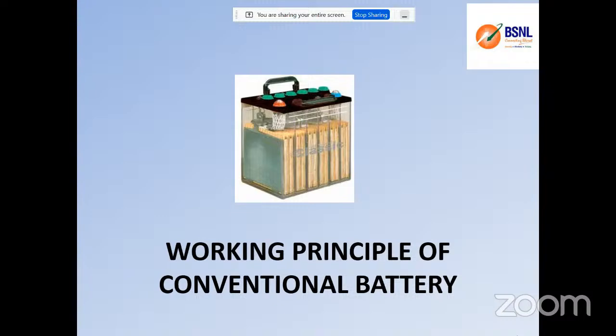But at residences, because of affordability and the cost-effective nature, though the UPS methodology is available, not all the loads are critical loads. So we neglect the non-critical loads and use the inverter model. So that, okay, if this goes off there is no problem, so I don't need battery backup for it, and even a smaller battery backup is enough for me, since I have only very limited critical loads. That is why the UPS models are segregated. So inverter models are more popular in our industry. Hope I made it clear about the logic of both UPS and inverter.